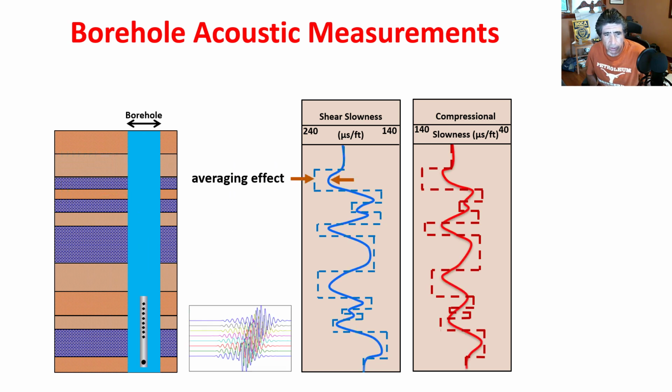And this tool is moving from the bottom up, and when you do those measurements, the mini seismograms are processed in real time, and we produce the logs that we have here, P wave velocity log or shear wave velocity log.